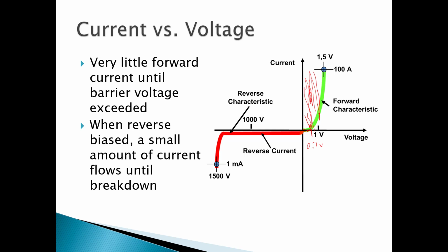Okay. In the reverse direction, no current flows. All I'm trying to show you is we think of the diode this way. I'll extend this down. We think of the diode this way. It's off, then it's completely on, and this is 0.7. And then if I go too far back, it's breakdown. Okay, this can often be quite a bit.